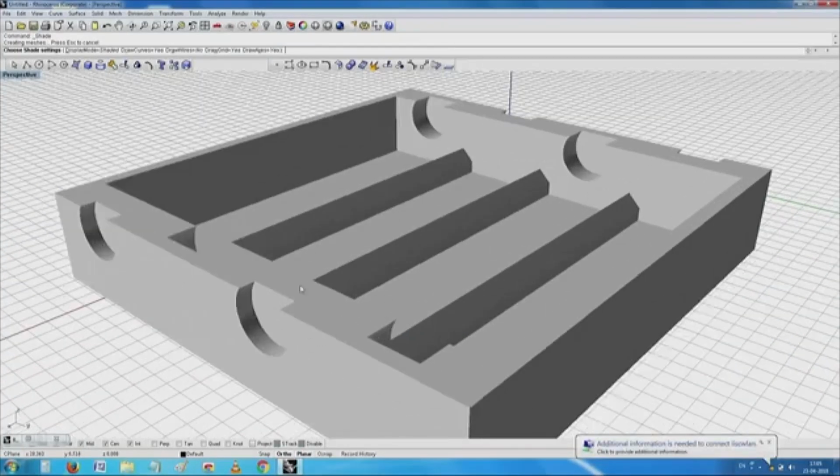Do we need a space here? Do we need a hole here? And can we make any of these openings later? Can we have a second operation? If you want to have a second operation, it is very much possible for you to make a small dimple or a small opening here, so that it is possible for you to enlarge it. Marking is already there. You can use probably a drill bit or a hand tool, and depending on the taps you have, can we tap a hole?